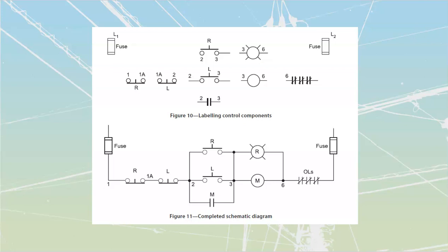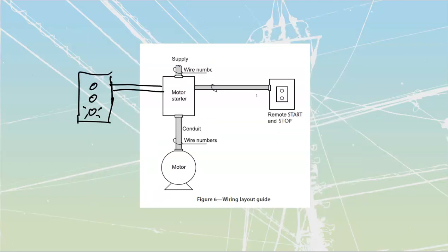Okay, so we're going to start with the right-hand box. My right-hand box has these over here, like that. Okay, that's inside of the right-hand box. How many wires, how many lines poke out the bubble? 1, 2, 3, 4, 5. Okay, we would need to have 5 conductors inside of my one conduit. Let's just place it on there. 5 conductors inside of that conduit over there.